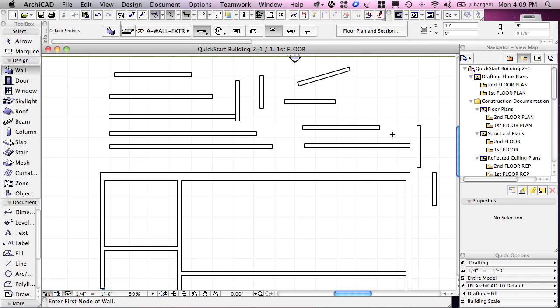So this is the way that you would use guidelines for lining things up when you're drawing. Now in terms of distances, when I use the measure tool, if I click on the measure icon, you'll see that there's some arbitrary numbers. It says a distance of 80 feet and a funny angle. As soon as I click, it goes to 0. So it's measuring from the last point that I clicked. This is sometimes called the edit origin.